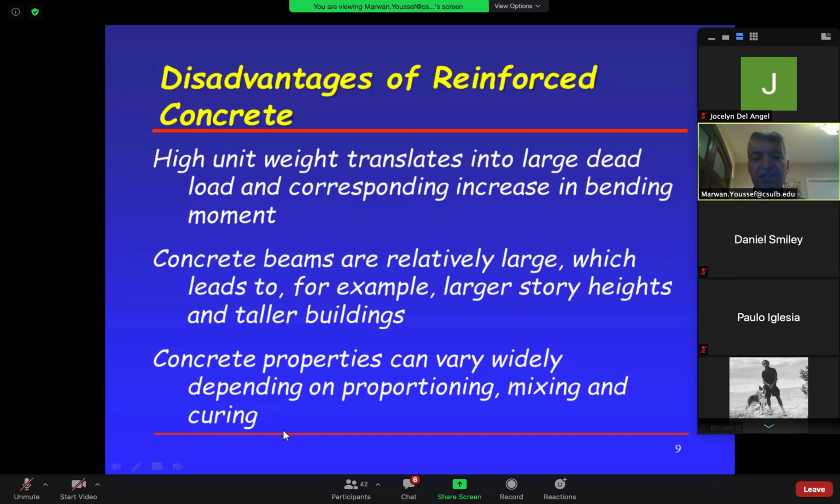And then curing. What is curing? A lot of people, you probably see them pour concrete today and then in the morning you see them putting water on it. They get some cold water, room temperature, and they put it on the concrete. When you put it on, you start seeing it fizzle. You start seeing bubbles coming out of that, right? Again, concrete loves water. So this is curing, because the idea is to keep it wet at least for 7 days. The more you keep it wet, the better it is, because the more you keep it wet, the better the chemical operation that's taking place, the heat of the hydration process is better.